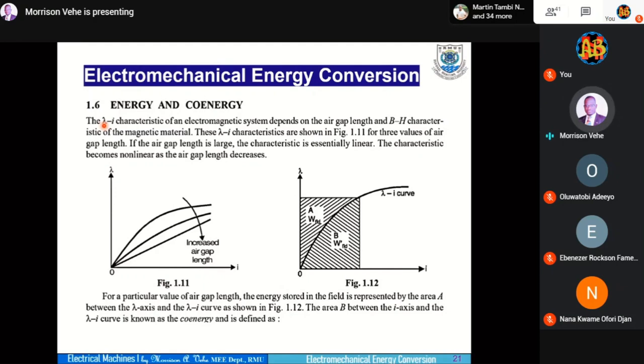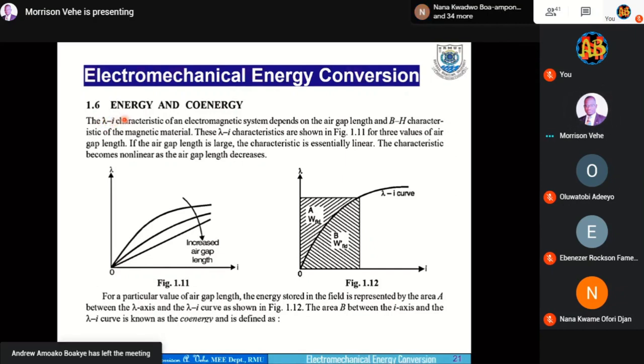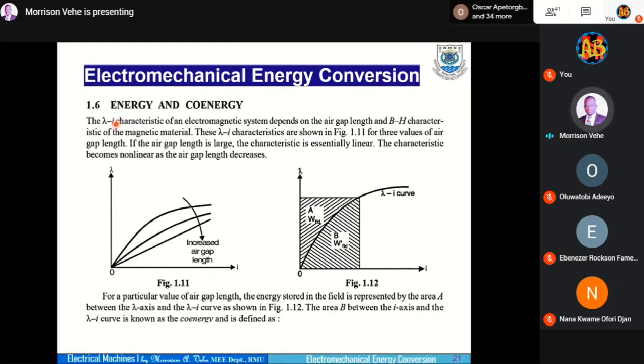especially in the core. If we wound the conductors on the core, it sets up flux, which links the entire core. It's not something that we can easily justify if we separate it. It's inseparable, the flux and then the current. That's why we keep saying lambda-I.